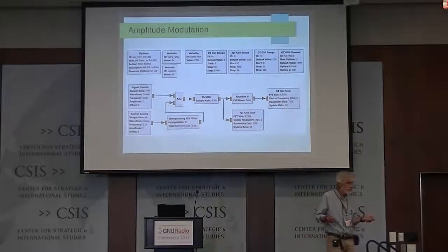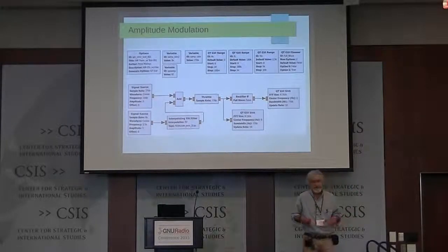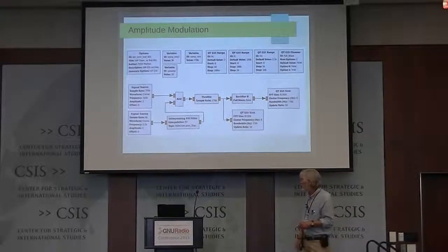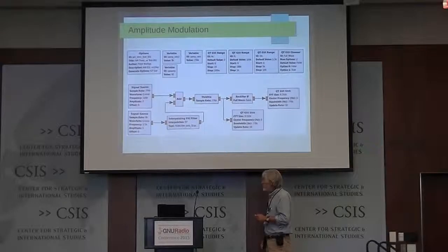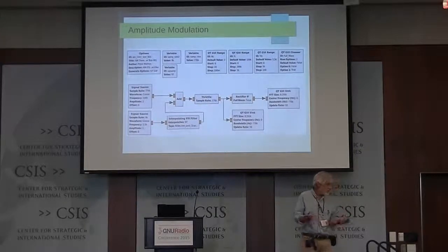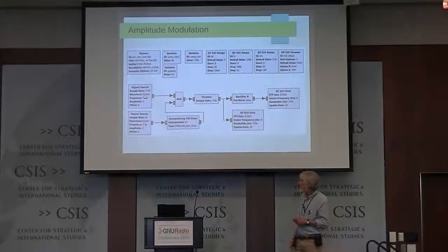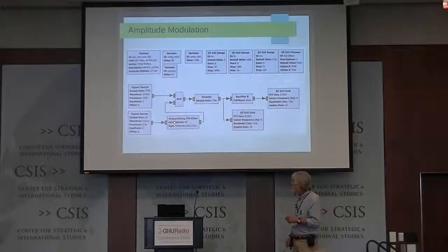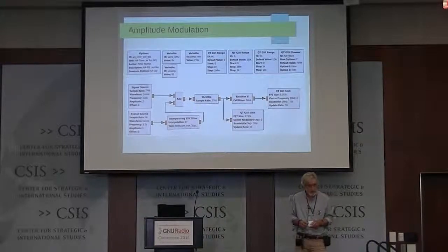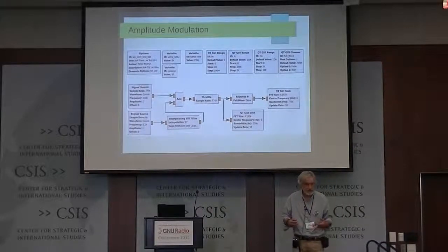Your signal source, which ideally is going to be some music or speech, is at a sampling rate of, say, 8,000 when you do amplitude modulation. But your carrier is going to be at least 100 kilohertz, maybe 1 megahertz or so. In order to make the two compatible, you have to move the sampling frequency high enough for the carrier, and then do the interpolating FIR filter to put your message signal up there.